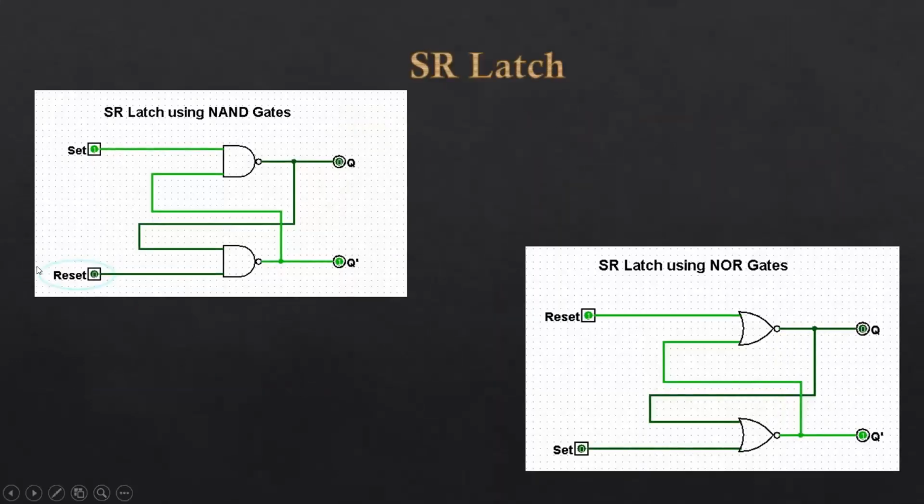See here, this shows the logic circuit for the SR latch. Here I use NAND gates to create the SR latch, and here I use NOR gates. Actually, we can draw an SR latch using NOR or NAND gates. Generally, NAND gates are preferred.